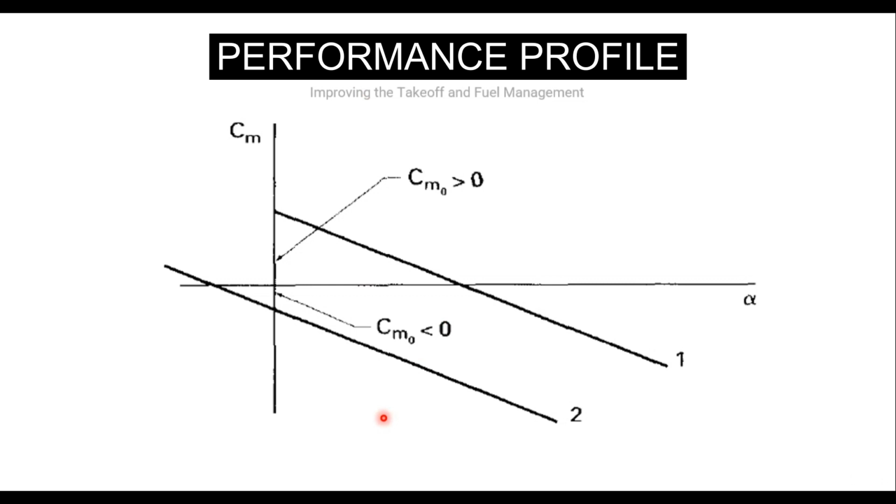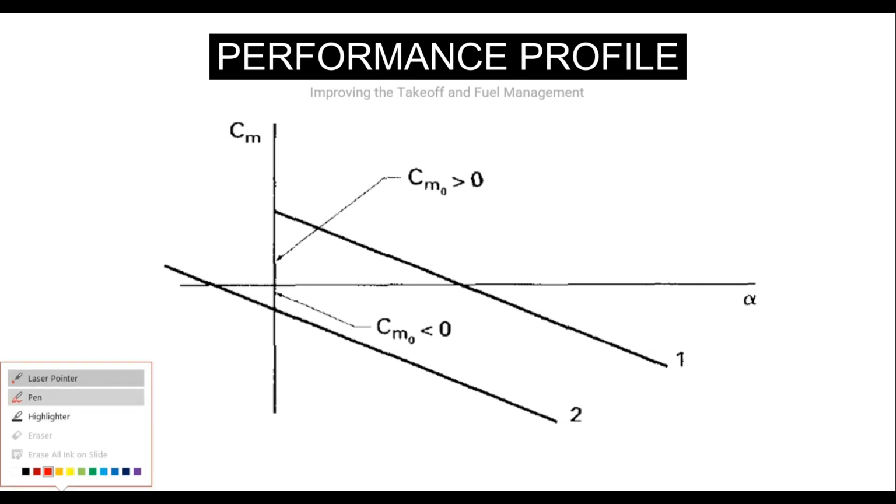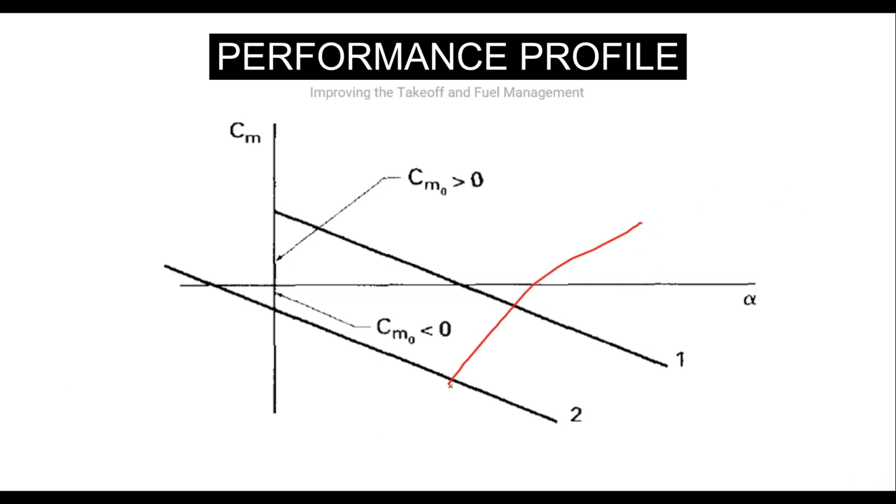But that doesn't mean that the fuel consumption will be better. The aircraft stability will be better, but the fuel consumption will not be better. So let me tell you the opposite. This is the last part we will talk about, so I'm leaving it to the end. If I'm moving the CG forward, this is a more stable aircraft.